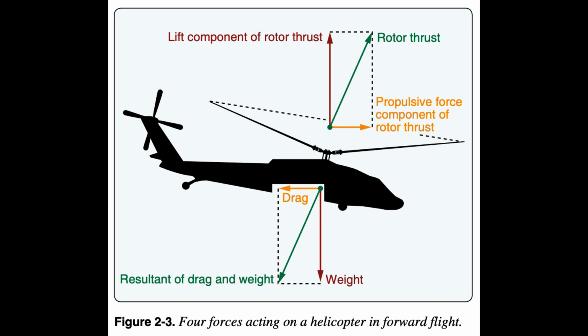With just the right amount of air passing over the blade, the upward force will equal 1 pound per square foot. This upward force is equal to, and acts opposite, the blade's weight of 100 pounds. So, if we now remove the stand, the blade will defy gravity and remain in its position, ignoring rearward drag for the moment. The force created by air moving over an object, or moving an object through the air, is called aerodynamic force. Aero means air. Dynamic means moving or motion.